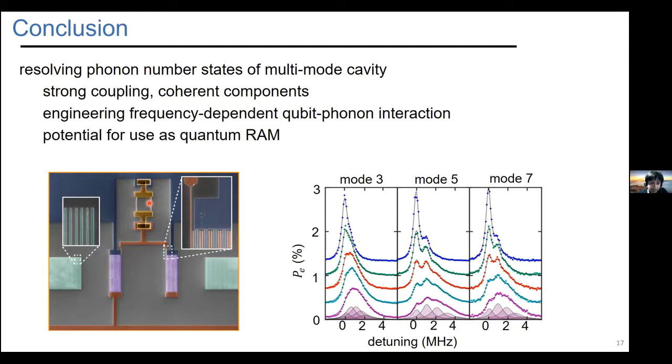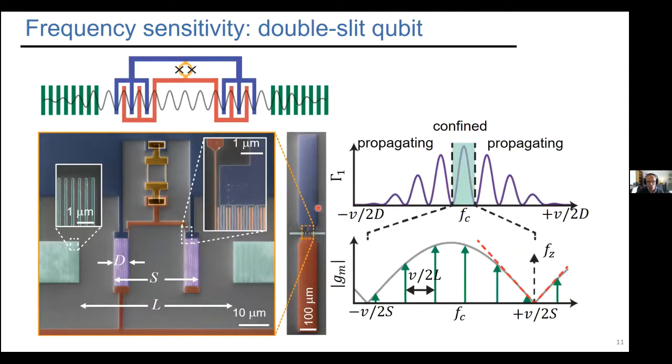And the red and the blue, they are both ground, or? Yeah, if you don't mind, I will go back to this picture. So red and blue are two different electrodes. They're separated. So the junction needs to shunt the red to the blue, because that's what the capacitance is between. And then the pink is just where red and blue are overlapped too finely to see in this image.